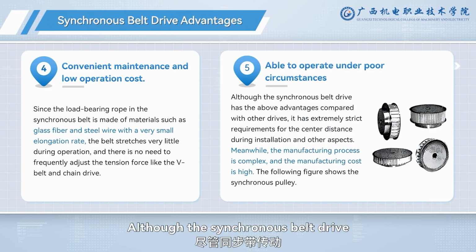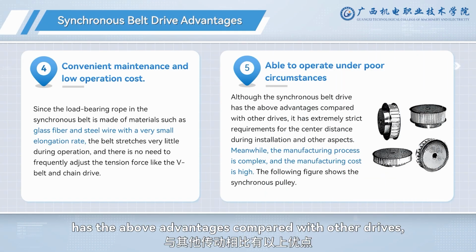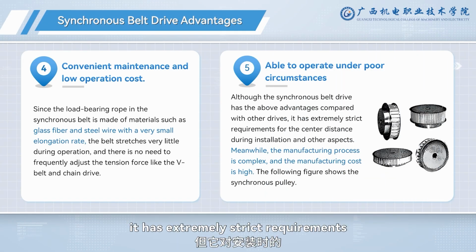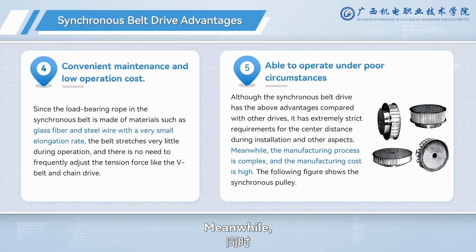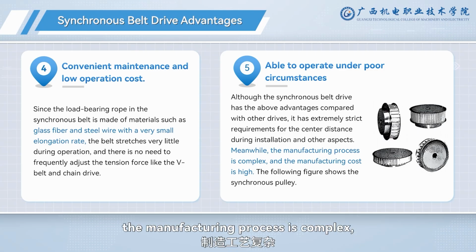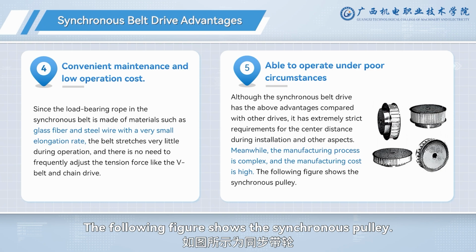Although the synchronous belt drive has the above advantages compared with other drives, it has extremely strict requirements for the center distance during installation and other aspects. Meanwhile, the manufacturing process is complex, and the manufacturing cost is high. The following figure shows the synchronous pulley.